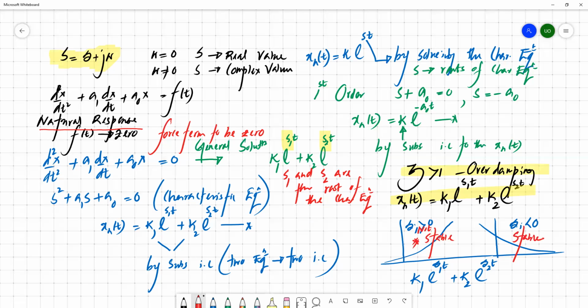Because we know that the initial condition is a temporary value stored in this inductor or capacitor. With these initial conditions, after a certain time, we know that a capacitor or inductor simply discharges to the rest of the circuit. So after a certain time, the effect of this initial condition should be nil, and the response would ideally converge to 0. If it is diverging, continuously increasing, then this system is not a stable system. So depending on the nature of the response, we can claim that it's stable or unstable.